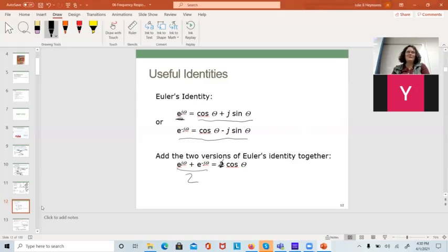We used fast Fourier transforms because you can take a fast Fourier transform of a real signal that doesn't look like a nice sinusoidal wave. You cannot do Laplace transforms on messy signals. There's no mathematical expression for them. And a lot of people, like some communications engineers, thought in the frequency domain, and data acquisition engineers thought in the time domain. And there was no going back and forth between there. You were either doing one or the other on whatever project you were working on.